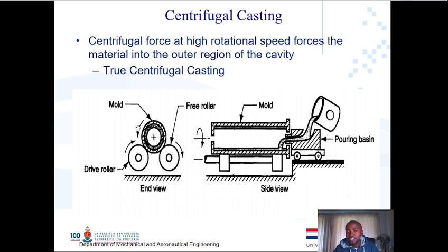For centrifugal casting we use it also to get hollow dimensions, but we are also concerned about the internal dimension. So you'll think of pipes. Some of the pipes are manufactured from centrifugal casting. On a pipe you'll have an outside diameter which is of your concern, and also your inside diameter which is your concern.